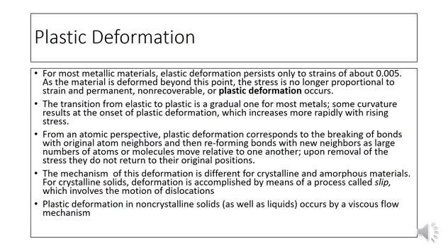But it has been observed that for most materials, elastic deformation only occurs up to about 0.005 strain. Beyond this point, most of the materials become plastically deformed. It's non-recoverable, or it becomes permanent. And the transition from elastic to plastic deformation is gradual, or very slow, and it's difficult to easily mark it out. This will be discussed later in the following slide.